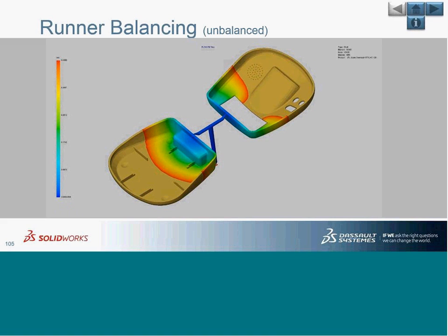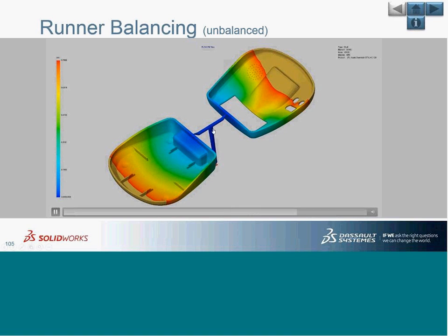We want to ensure that it is compressed and the same density is present uniformly. In such cases, we want both these parts to get filled at the same time. So we need to play with the size of the runners and gates, change them, and ensure the sizes help in having a different quantity of plastic in different parts and help in filling them at the right time.